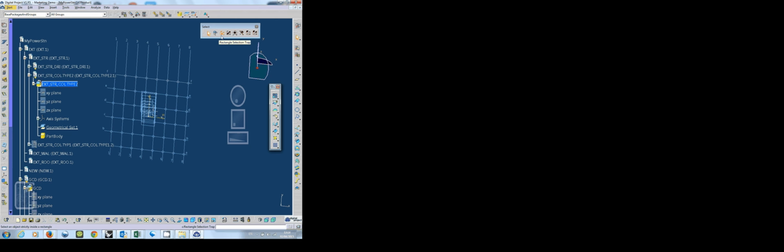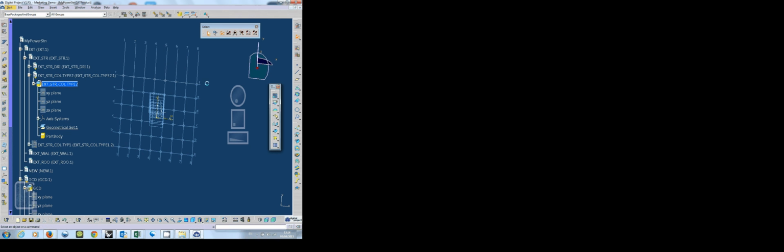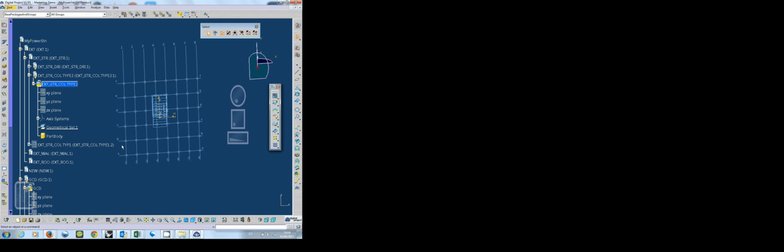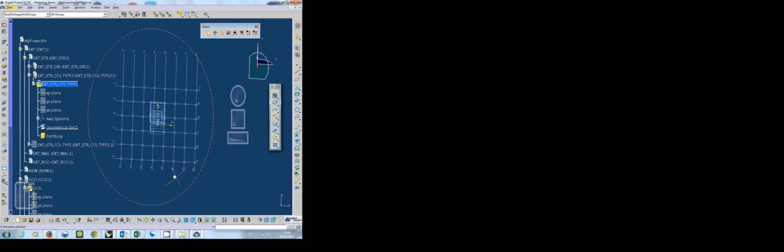Or you just make sure everything is inside your trap. So if I do this, I can make a frame selection by putting this, right? And I select it. And if you want to keep adding to the selection, hold Control down. So now I'm just trying the first row of columns. All right. So I pre-select those intersecting points.